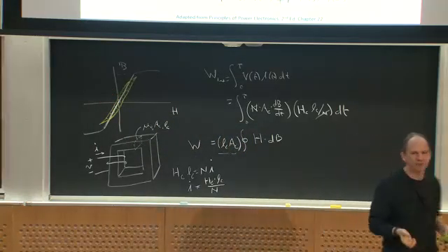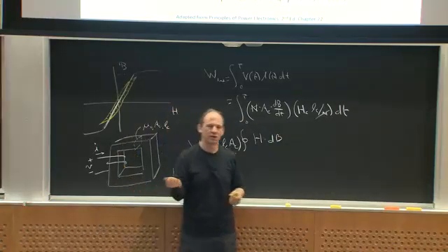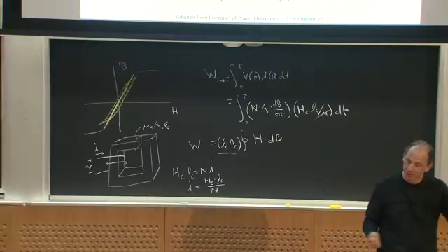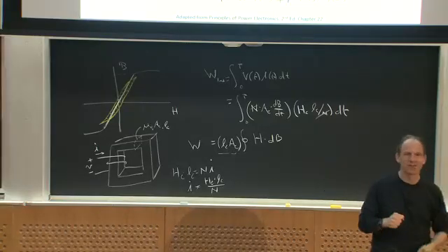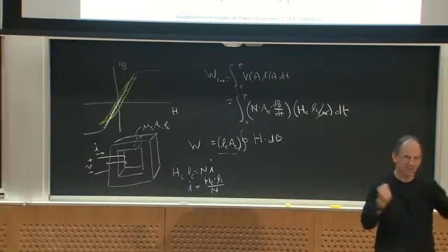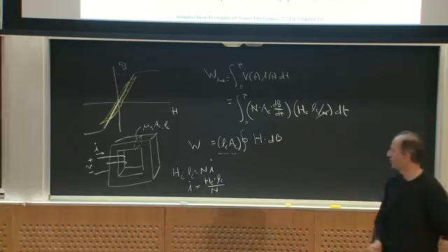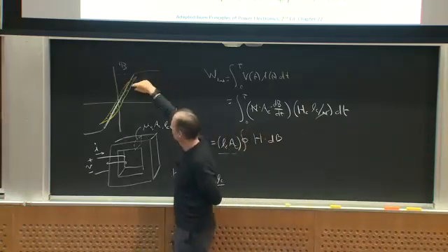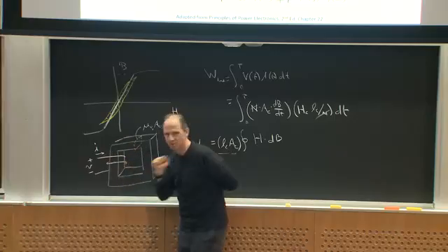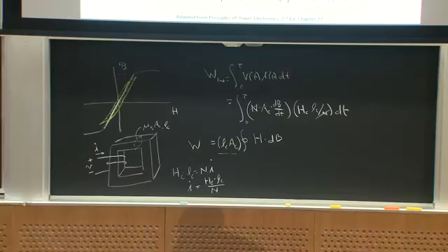Unfortunately, when you get higher in frequency, where does this loss come from, I should say? It's because you're doing work to move magnetic domains around, right? They're mechanically moving around. And by the way, when the magnetic domains jump, they introduce little eddy currents in the material, and so that generates loss, right? So you do have a bunch of loss moving the magnetic domains around, and hence that appears as this net loss that even if you ignored winding loss, there's some additional loss by swinging AC flux in the core. Okay?